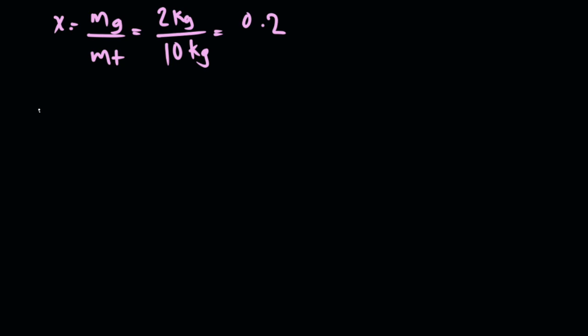From our previous discussion, we talked about the specific volume of the mixture inside the saturation curve. We're just going to call that V, with no subscript, and that is equal to V sub F plus x, the quality, times V sub FG.